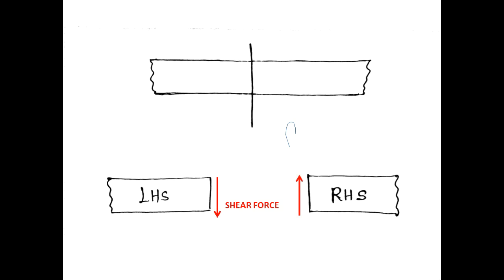This is called the shear force. This shear force acts parallel to the surface. Normally, positive shear force on the LHS part is considered downward, and positive shear force on the RHS part is considered upward, in the direction shown in the slide.